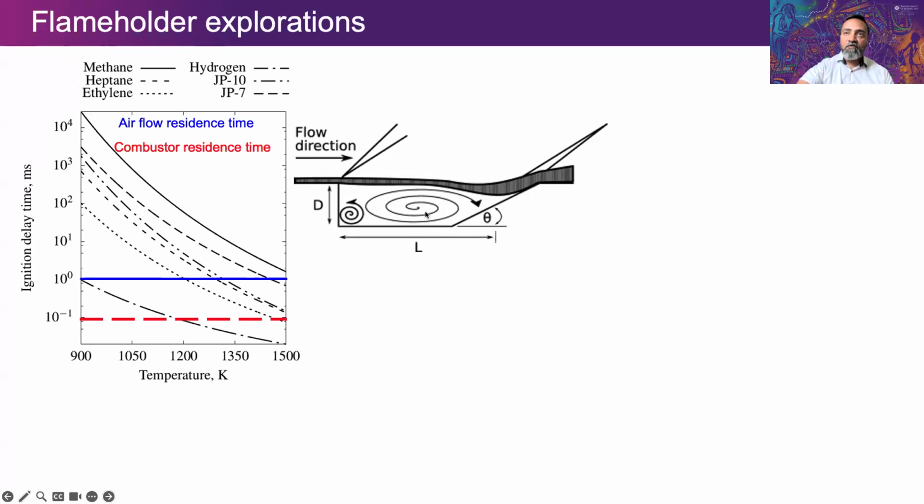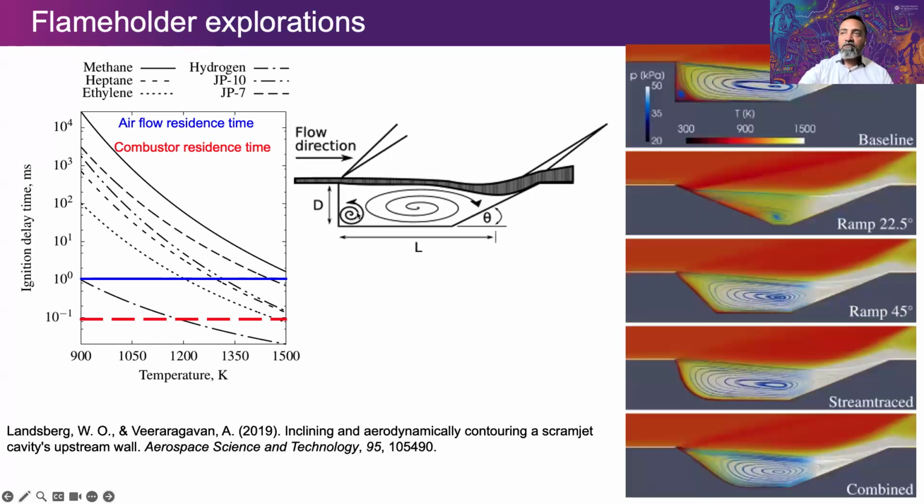We looked at this and went, we understand this vortex, it's needed for mixing. This is where you increase your residence time, right? So normal residence time, if it's flying through, it's going at this speed, but by slowing it and churning it here, we're dramatically moving this line upwards in terms of the residence time being much higher, and we can then definitely burn some of the other fuels. But do you need this little vortex that's spinning as a secondary thing that comes about, causes drag? We did a series of numerical simulations that removed that shape and changed it to a shape that does not build that secondary vortex. And all our simulations indicated the performance will be similar, if not better, and the drag profile might actually be better.